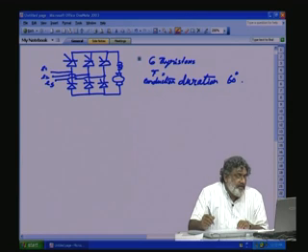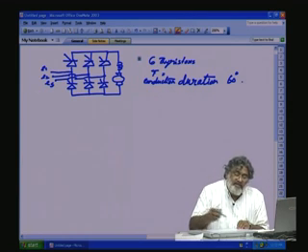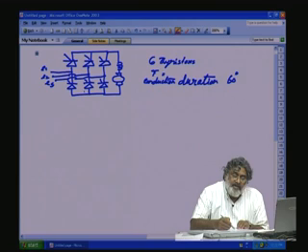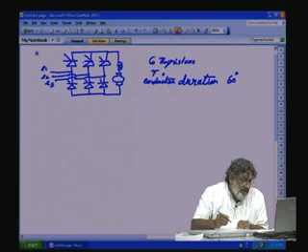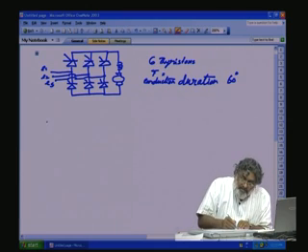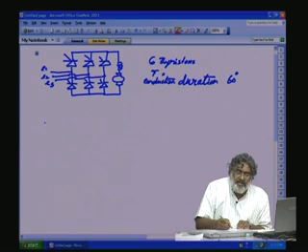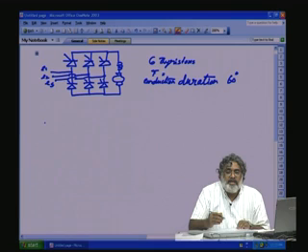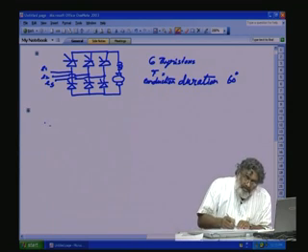Okay. Now, previously when we discussed the top and bottom half bridge converters, each thyristor will be conducting for 120 degree, and every 120 degree there is a commutation process initiated. Now, here how will it happen? Let us first draw the 3-phase mains waveform. All these phase control converters using thyristors use natural commutation. That means the incoming thyristor will force the previously conducting thyristor off by applying reverse voltage across it from the incoming phase. So, let us draw the 3-phase waveform.